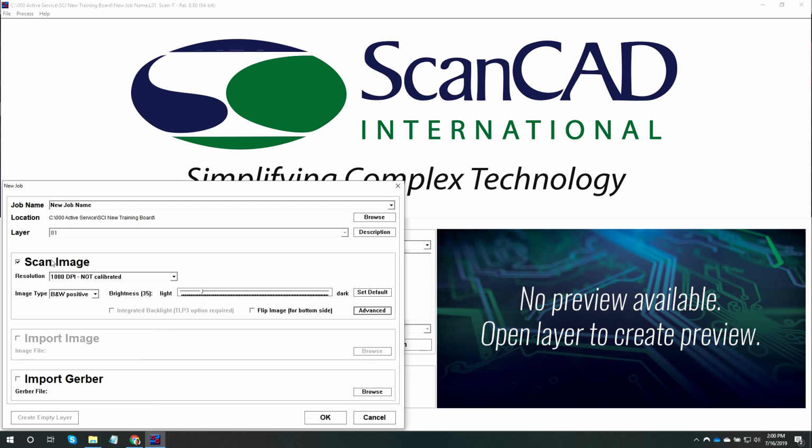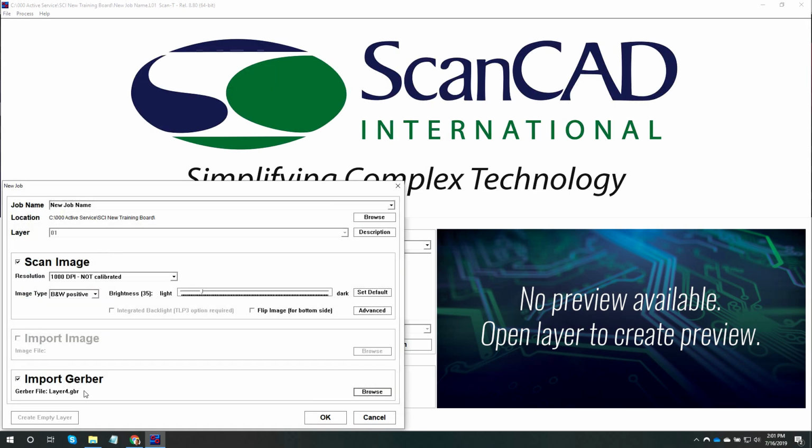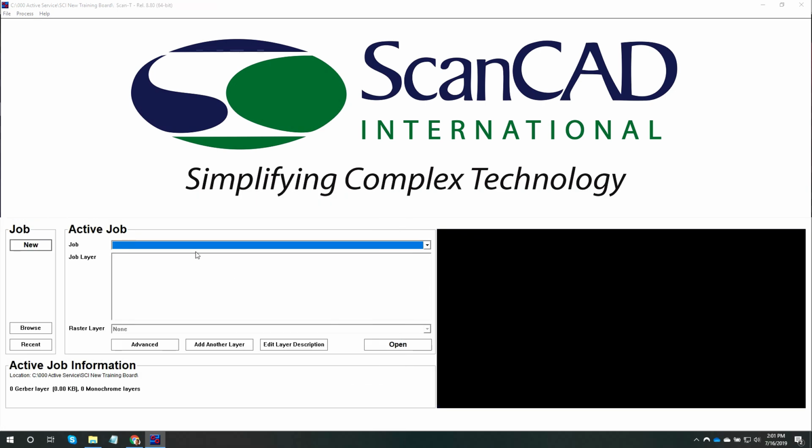If I want to scan and import a Gerber file for an inspection workflow, then I'm simply going to check the scan image and configure my scan settings, check the imported Gerber file, and use the Browse button to identify a Gerber file. And then hit OK, and I will scan in that layer and import that Gerber file.